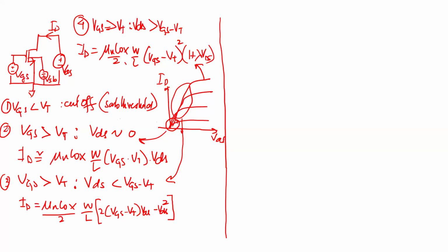Okay. But like I said yesterday or the day before, when I started designing, I kind of just took all the mods, which then just looks like the NMOS. It's just mu P, VTP, VDS instead of VSD and so on. But at least you should be very comfortable with the direction of the current. Like yesterday, I saw people just substituted the NMOS with the PMOS. You do that, it's all off, right? It doesn't work. So that's why the PMOSs are always referenced to VDD.